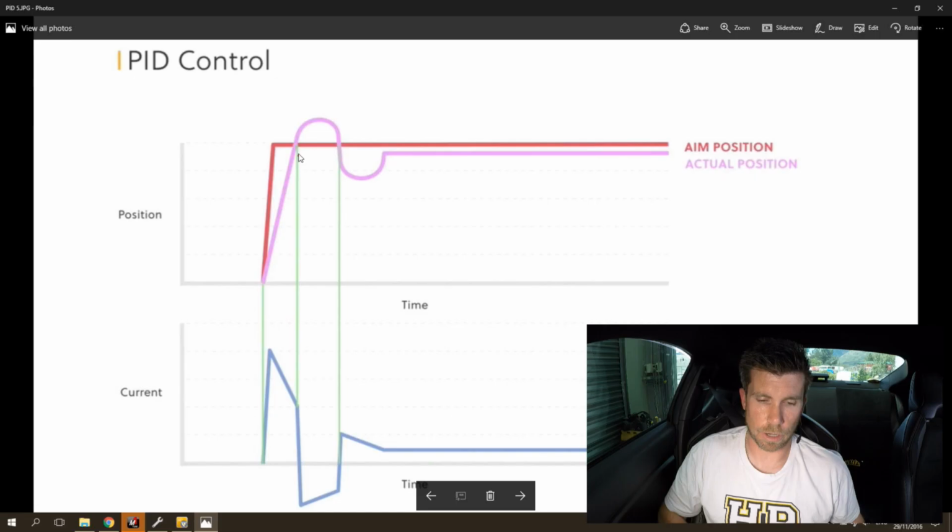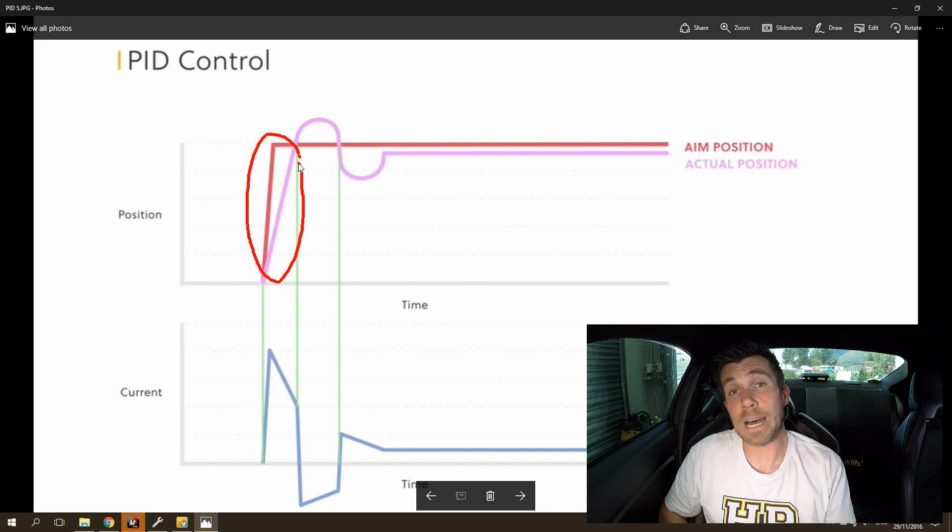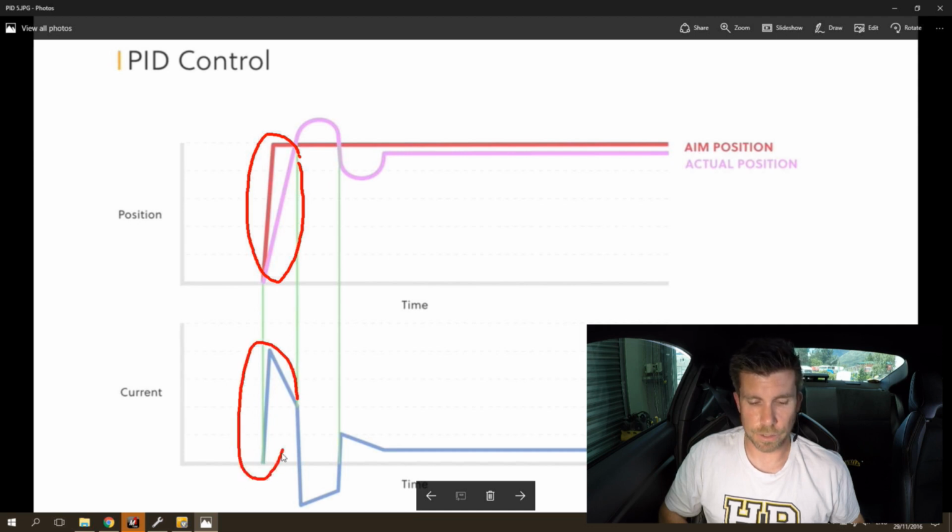Okay, so in our first example here, we have just purely proportional gain, and we've got no derivative. So what we can see here is in this part of our diagram, we have an error where we are below the target. So in response to this, the ECU provides a positive drive to our DC drive-by-wire throttle motor, so it's driving it towards our target.